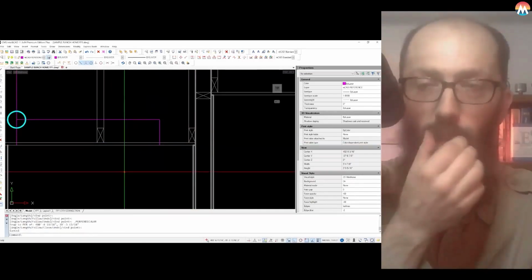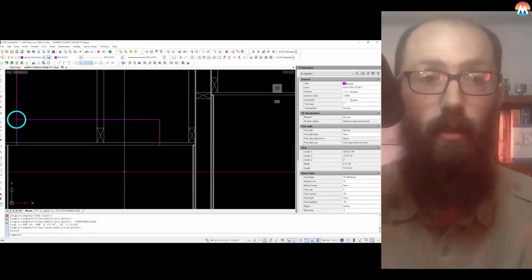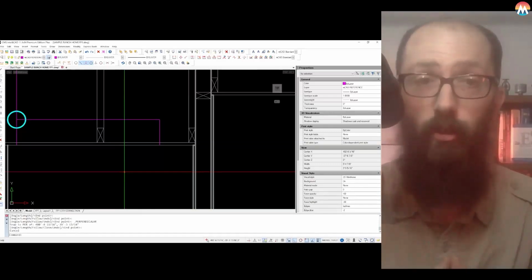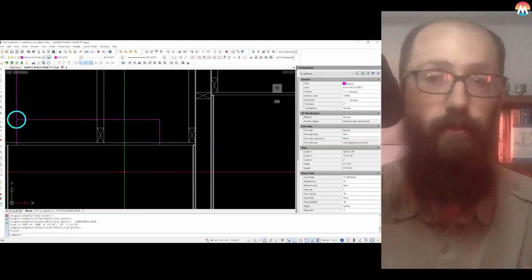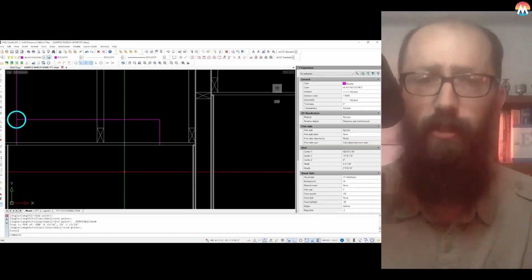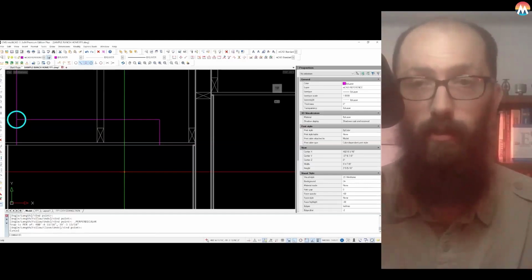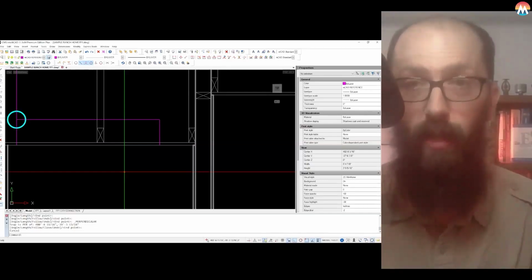Now the way that we show sprinklers in a cross section is over exaggerated, as always. Like on the plan, it's way larger than real life, and we show it as coming down through the ceiling like a pendant would. Again, way larger than real life. But just in this simplified version, we're using a concealed head, so it's not going to come down through the ceiling, but this is just to make it clear. This is how we represent on cross sections where a sprinkler is at in the pendant position.